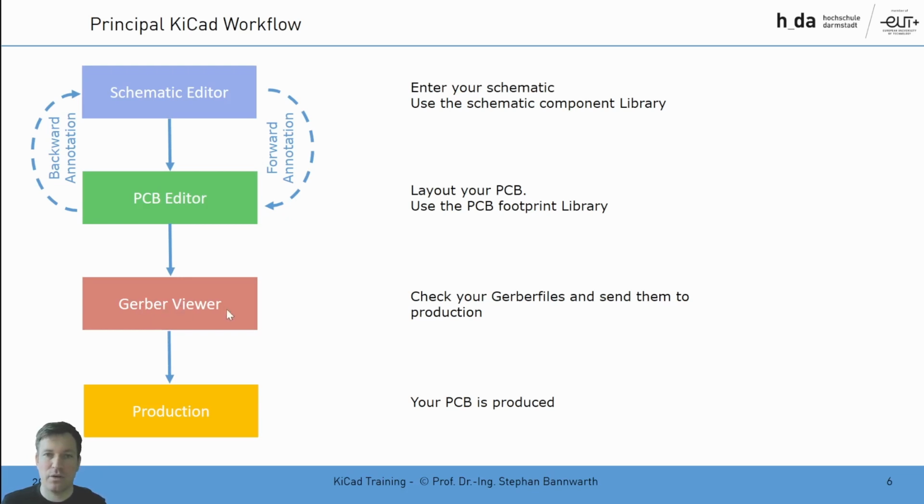You use the Gerber viewer to compare manually the Gerber files view of your PCB with the PCB editor view. In order this is the same, and you have to ensure the electrical connections are proper. Then you will send the Gerber files and the drill files to the manufacturer, and after some days or weeks, your nicely designed PCBs will be sent back to you from the manufacturer.